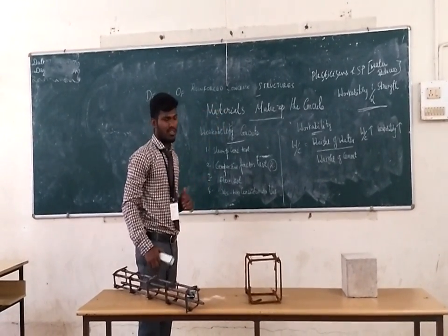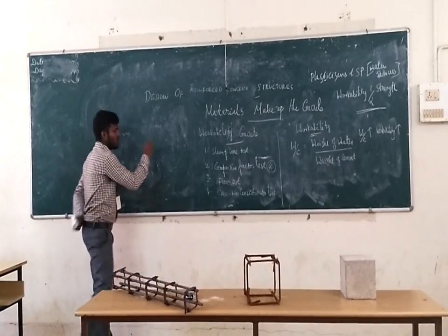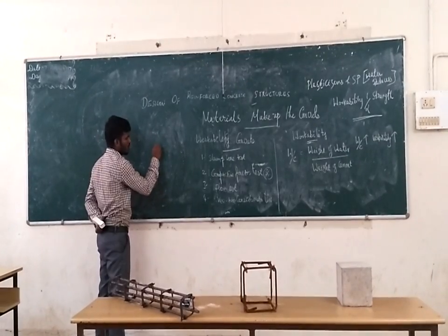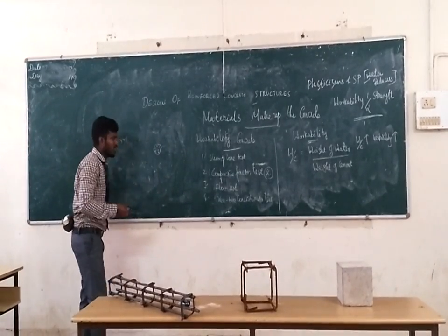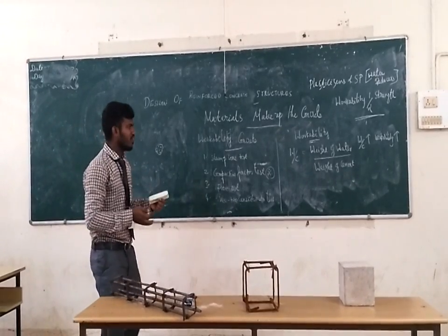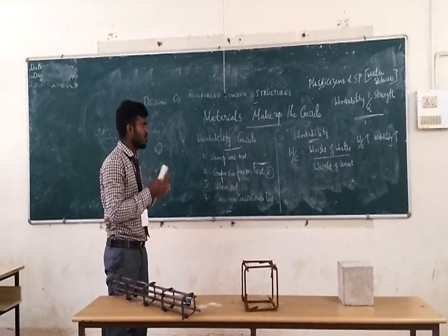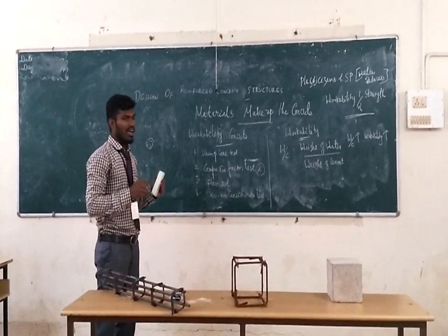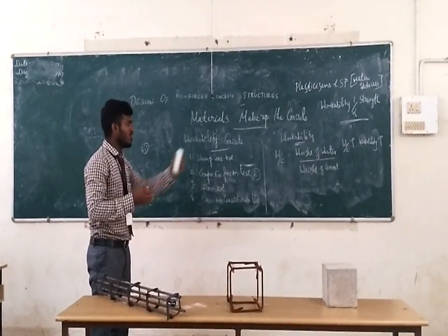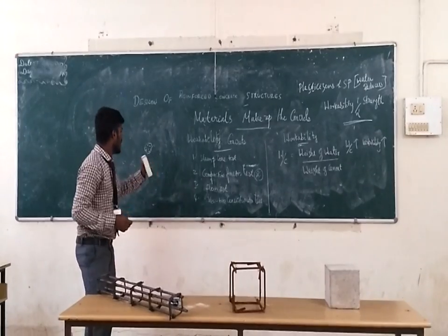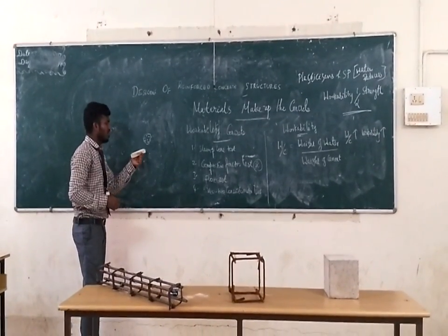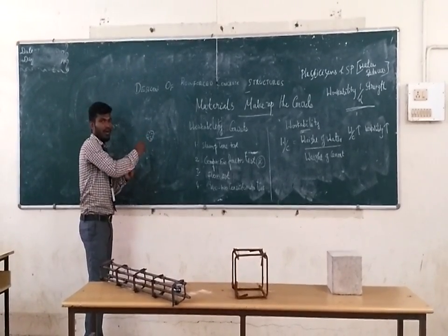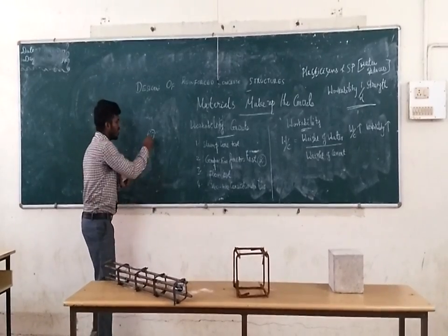We have to design the water cement ratio for the respective strength of concrete, and we must not add even a single percent more water than that. What actually happens in concrete is that when we add water, the cement particles surround the water molecules and entrap the water.